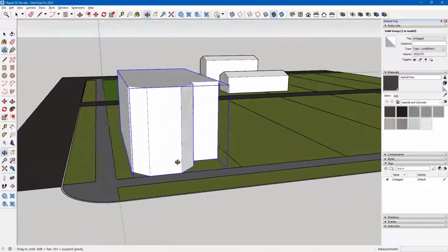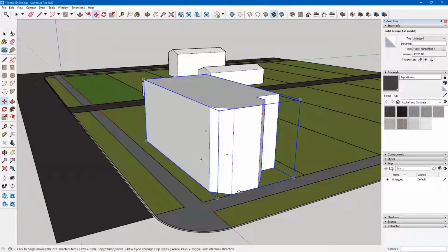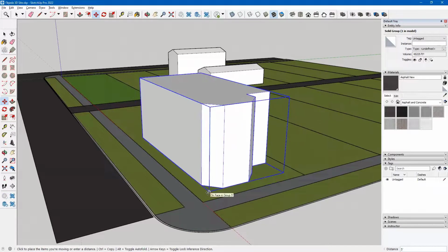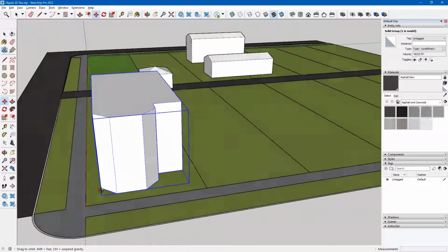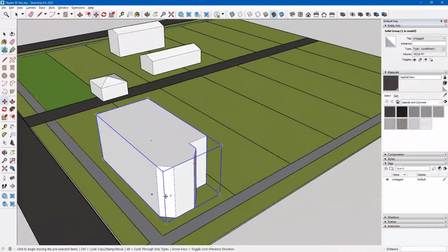And this is an apartment building and it shouldn't really be on the property like that. So I'm going to set it back a little bit. So I'm going to move it from this corner and I'll push it back, and 5 feet seems like an okay distance. So it's snapping to 5 feet since that's what I typed in a second ago. I'll keep that distance. All I have to do is click because it's showing that distance for me. So I'll click and I have that building in place. Now it's time to put the other two buildings in.